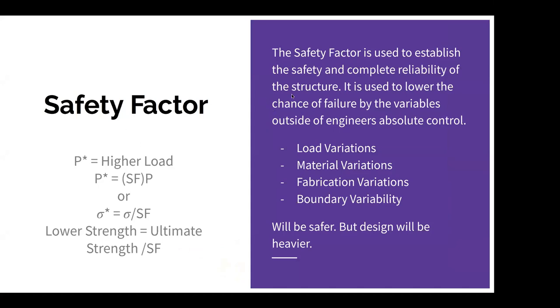So safety factor, I talked about safety factor. It's mainly dependent on load variations, material variations, fabrication variations, and boundary variability. We can't control everything, even though we're calculating everything.